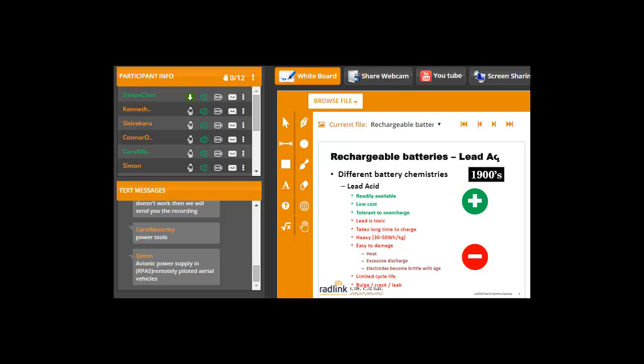So in other words, you dump the entire charge from the battery in just 6 minutes. So you might charge it over a 60-minute or 30-minute time, but you use it all in 6 minutes. And so these are being used in high power density products like power tools, medical devices, and electric cars. This one also has a thermal runaway problem. It's at about 250 degrees C.